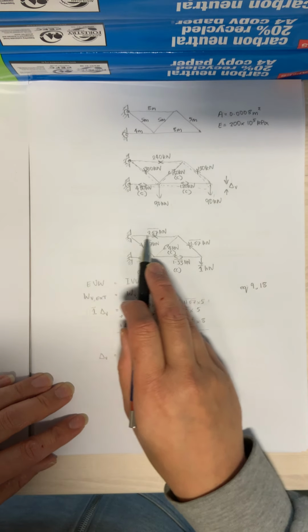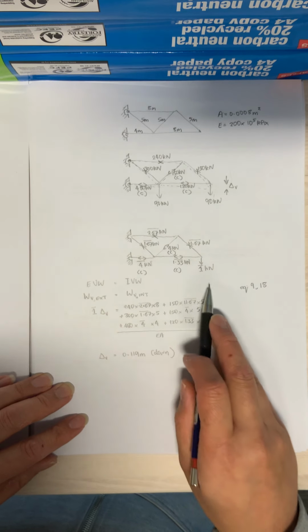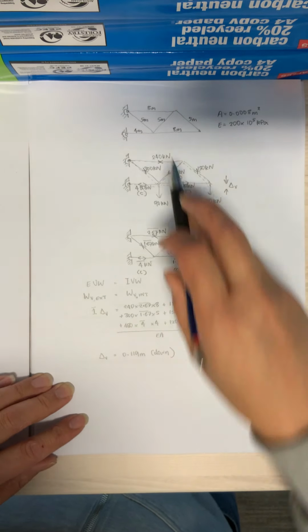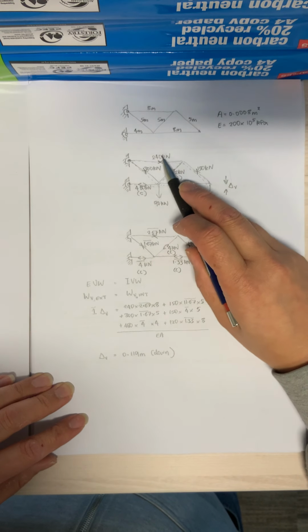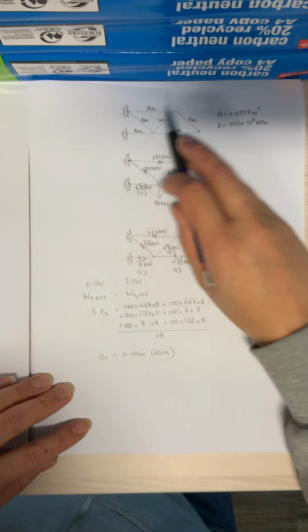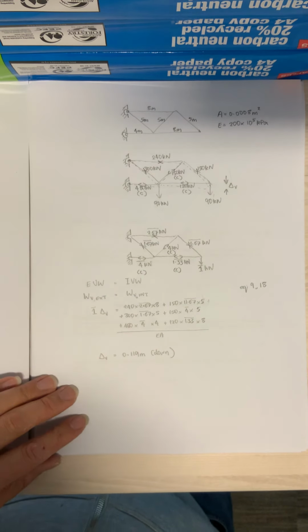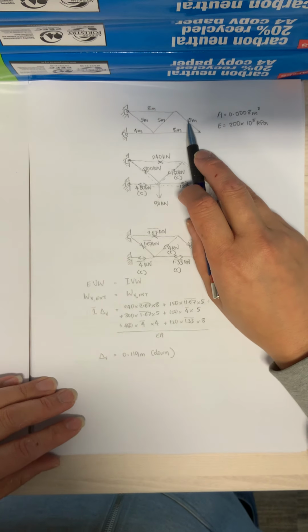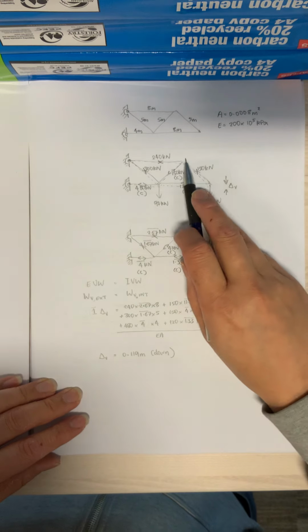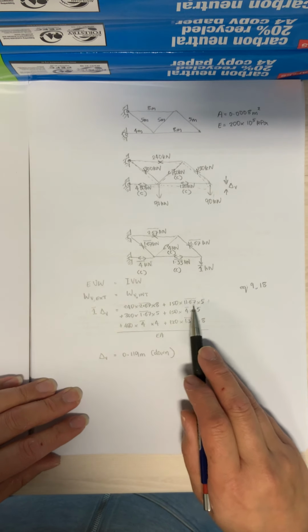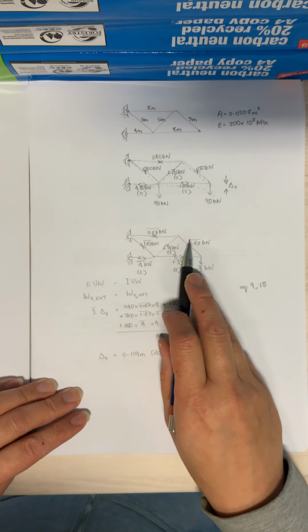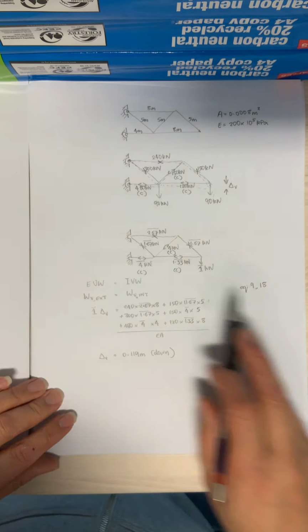and then this 2.67, obtained from method of sections or method of joints for a 1 bar kilonewton, you multiply that. So it'd be that value multiplied by that value multiplied by that value, which you can see there. That is for the first member. And then we've got the next member there. So this member here is of length 5. It's got 150 acting in it, and it's got 1.67 bar in the virtual system.